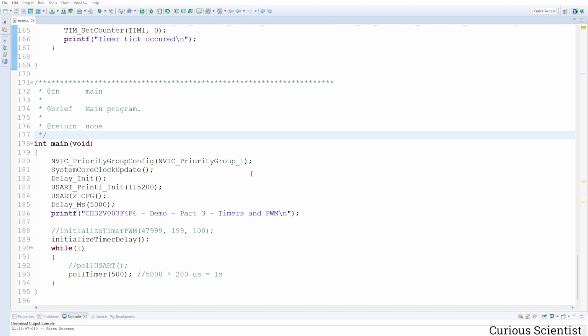So for example, you have a temperature sensor attached to the microcontroller and you want to read it every 1 second. You don't need to delay for 1 second and then read it and then update the display, but you can do something else. For example, read another sensor and then read the temperature sensor after 1 second elapsed, and then jump to the next task.